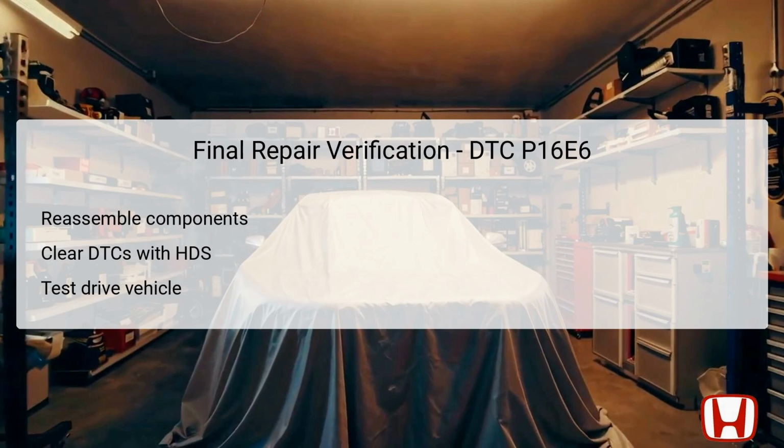After completing the necessary repairs for DTC P16E6, it's vital to verify that those repairs were successful. Begin by reassembling any components that were removed during the diagnostic process, ensuring all connectors are securely reattached. Subsequently, clear any DTCs that may currently reside in the vehicle's computer using the Honda Diagnostic System, HDS. This step resets any malfunction indicators, paving the way for subsequent operational tests. After clearing, perform a thorough test drive to assess whether the vehicle operates correctly without returning the previous fault. Successful verification ensures that the issue has been fully resolved, restoring the vehicle's functionality.